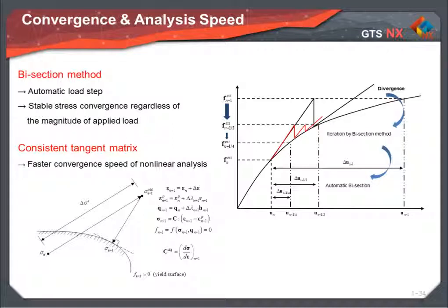When the solution is determined to diverge, the nonlinear analysis solution is judged to have possible divergence, and necessary measures are taken on the algorithm, such as recalculation of the stiffness matrix or load bisection. Load bisection is applied when the increment of the current load step is too large to obtain a convergent solution, such as when the solution diverges or when the number of required iterative calculations is larger than the user-defined maximum number. By restarting the iterative calculation through bisecting the current load increment, an inappropriate load increment size can be dealt with in a flexible manner.